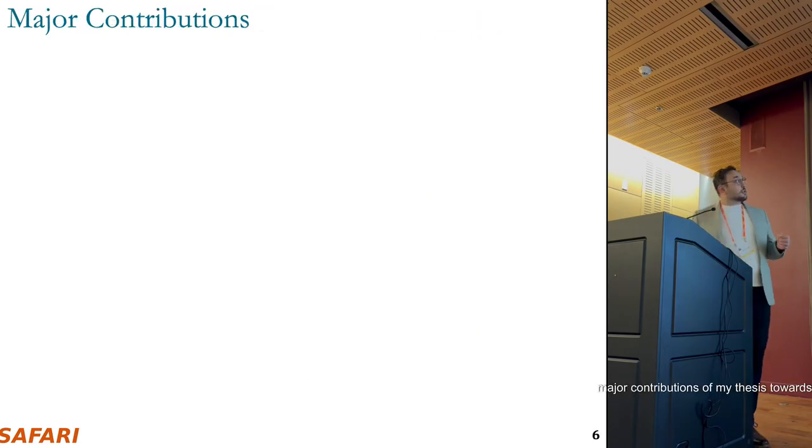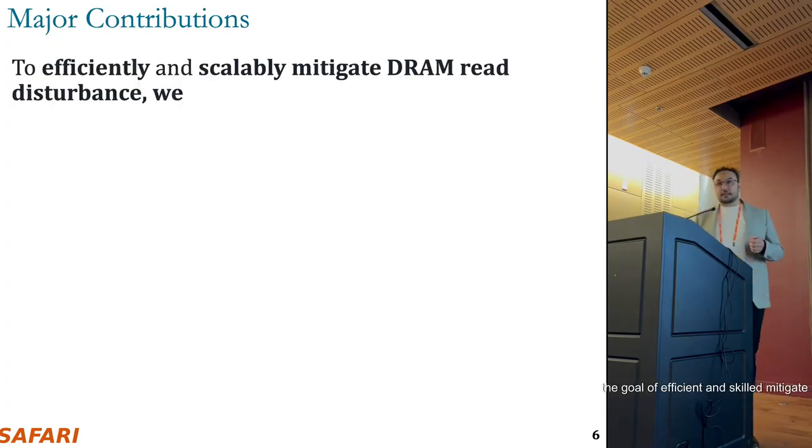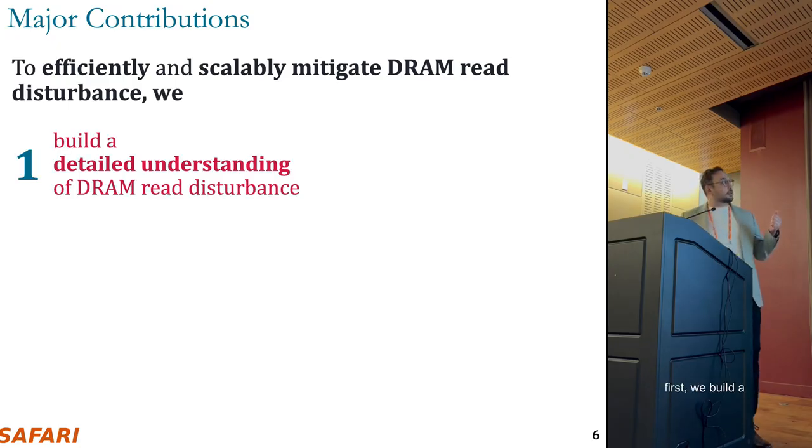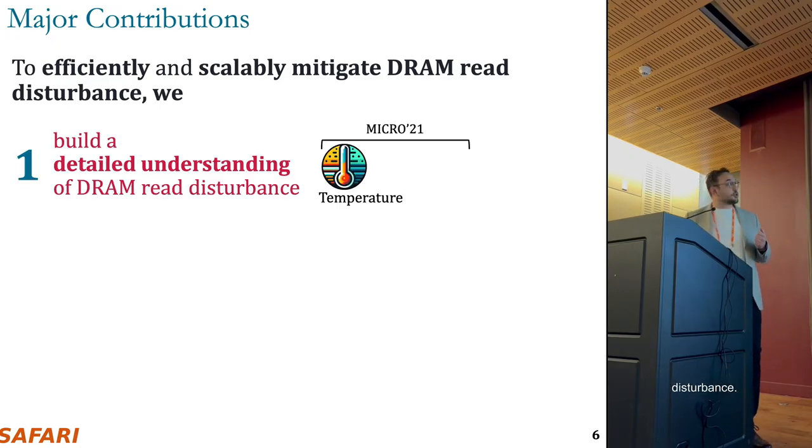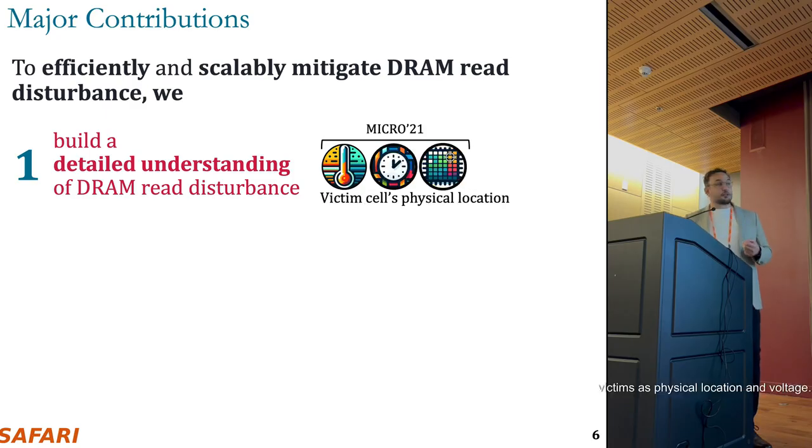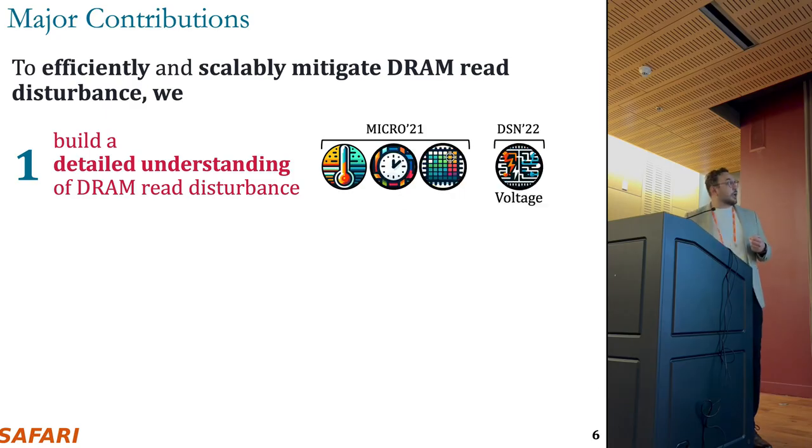The major contributions of my thesis towards the goal of efficiently and scalably mitigating DRAM read disturbance are, first, we built a detailed understanding of DRAM read disturbance. To this end, we look at Rowhammer sensitivities with varying temperature, memory access patterns, victim cells' physical location, and voltage.